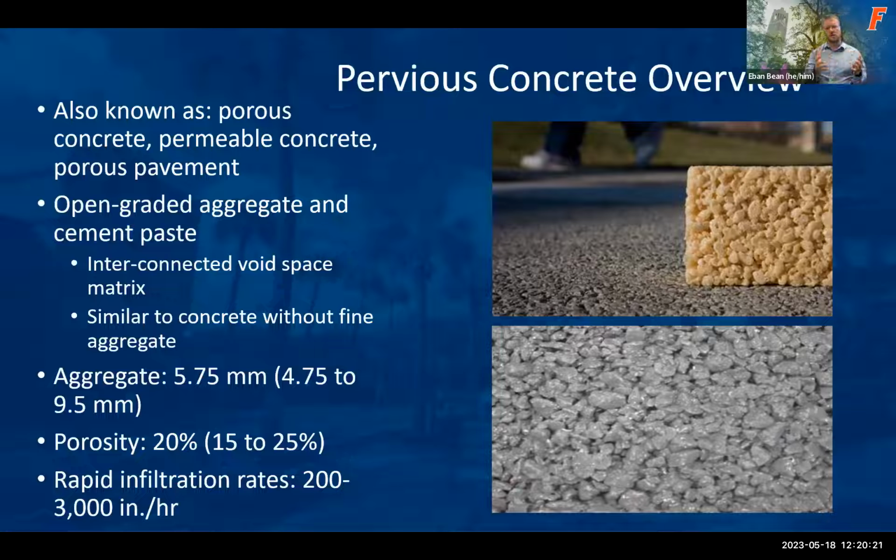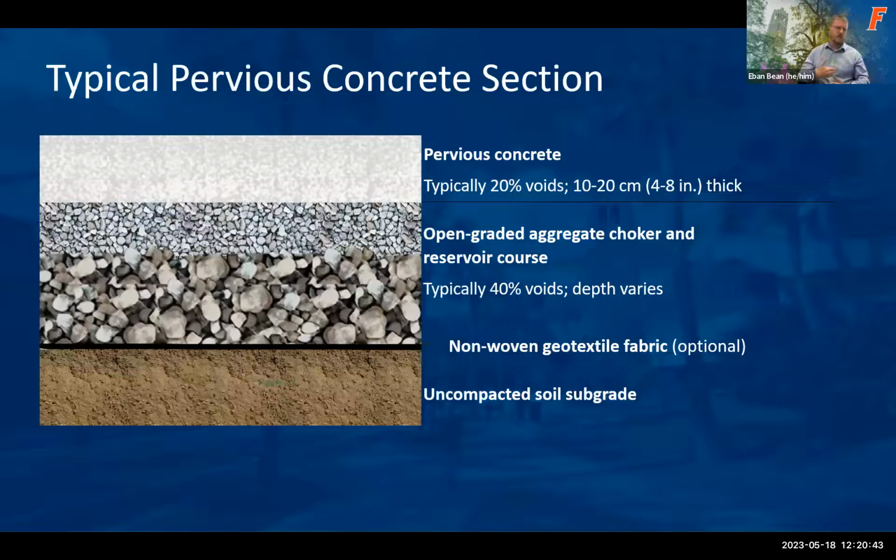So really, when you start to think about a 1-to-1 ratio of impervious to pervious, you're looking at double the rainfall rates. And let's say 10 inches in an hour. That's pretty intense rainfall. That would be 20 inches per hour. We're still nowhere near 200 to 3,000 inches per hour. The issues with clogging come up whenever we don't maintain for a long period of time, and that infiltration rate, whatever the type of pavement is, slowly declines, and it never seems like it's having an issue until it really gets to where it's really clogged and not been maintained, and that's when we have to address it.